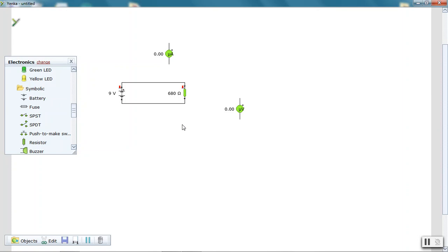There are two quantities that you will be measuring. One is the voltage, the energy per charge, or more specifically, the electric potential difference between 2 points on the circuit. So a voltmeter has to be connected one end at one point of the circuit, the other end at another point of the circuit, because it measures a difference. So I'll just move it over here.